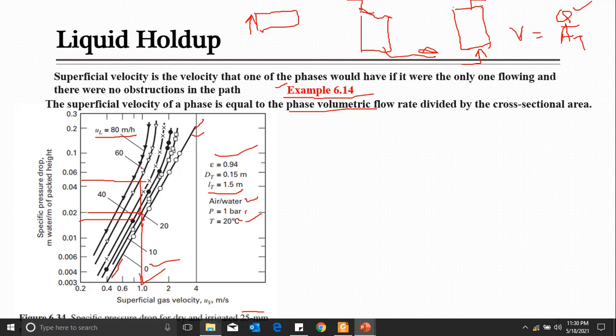So here you can observe another trend. If you look at these lines for the liquid flow rate, the initial one is for the dry case, a totally straight line, where the overall pressure drop is changing. I can't say linearly because these are log plots, but it remains straight. Still there will be pressure drop, but that follows some trend.